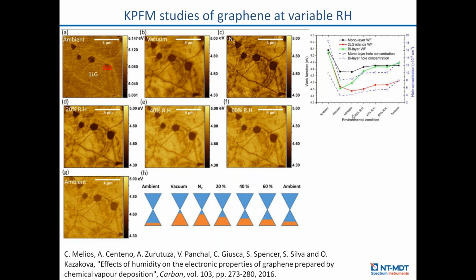40% of relative humidity. So that means that, first of all, if you make electrostatical studies of such samples as graphene or other two-dimensional structures, you must take this humidity into consideration. And the second thing is that the devices which work on the basis of graphene or other graphene-like materials should be encapsulated in real devices.